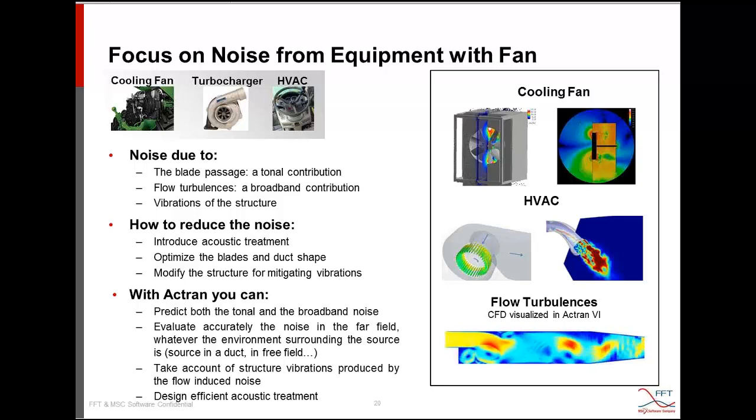So we have already addressed the noise coming from the powertrain, the intake and the exhaust. Now I'm going to talk about equipment with fan. Equipment with fan, like cooling fans or HVAC, also makes a lot of noise. The fan noise is far more important for a tractor or an excavator than for a car, because engines are bigger, first, and then vehicles are slow or stationary. So the airflow is very low, and the fan has a more important role for cooling the engine, and is thus bigger and produces more noise.